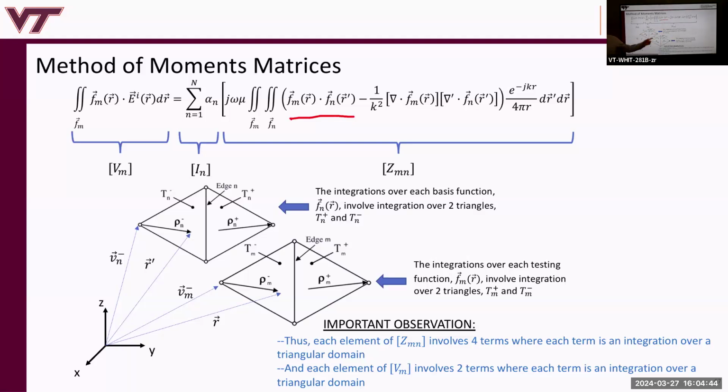If you construct this integral equation, the same one, the EFIE, using a mixed potential approach, then you'll recognize that this comes from the vector potential terms, magnetic vector potential. All right, then you have this other component here, which you'll note doesn't vary linearly, right?